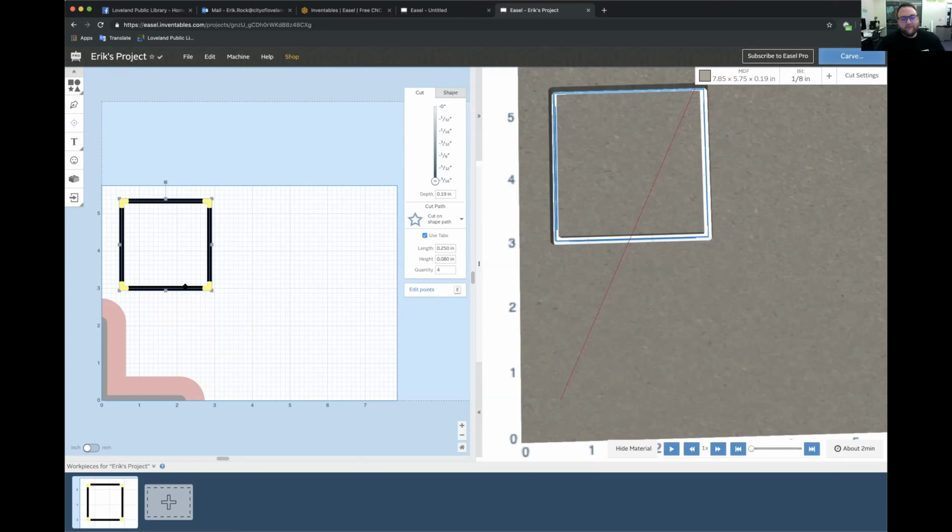We've done hundreds and hundreds of these at this point, and we've tested almost every possible error. That one's pretty common. So the tabs are going to protect that shape that you're cutting out. If you have tabs, you can actually move where they're at. Let's say you really want them on the centers so that you get nice sharp corners. It doesn't show you on the preview because it assumes it's going to carve out all the material, but basically it's just hopping over the material there.